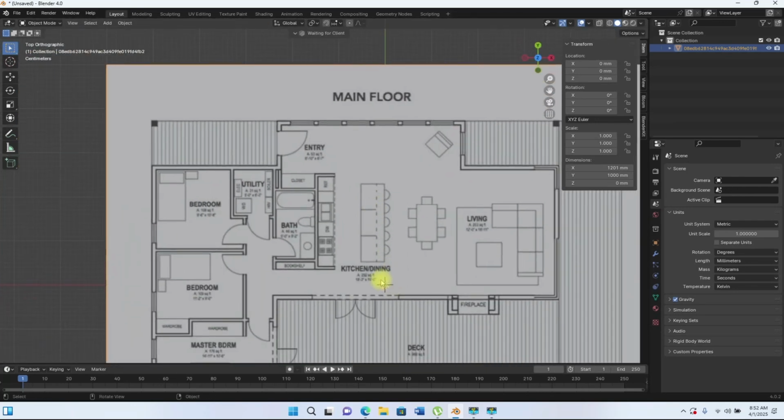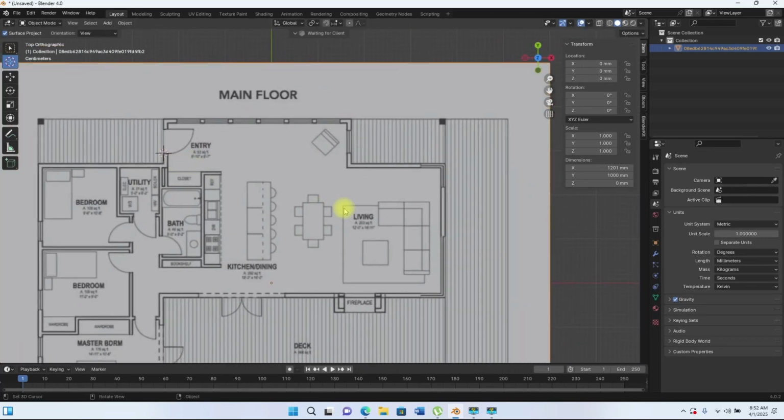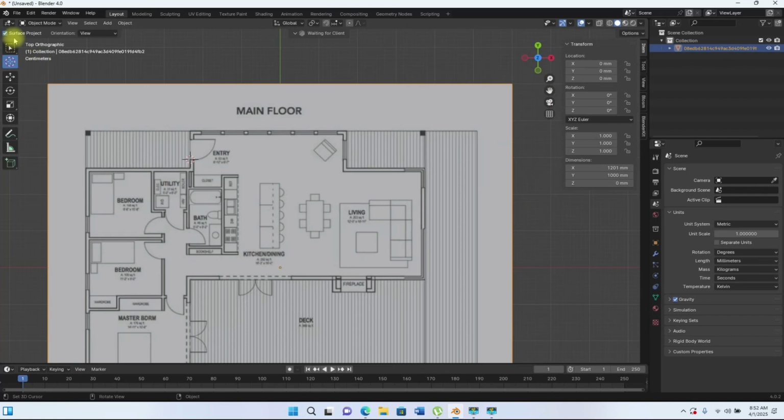So I need to bring my cursor to this point, and then that cursor will in turn allow me to bring the origin points here that I can now start scaling up. For me to bring the cursor, just click on this cursor icon on your toolbar, and then click anywhere here, just the line. And then I have my cursor there. At this point, if I scale, it's still scaling from this origin point. But the good thing is now I have this cursor added there.